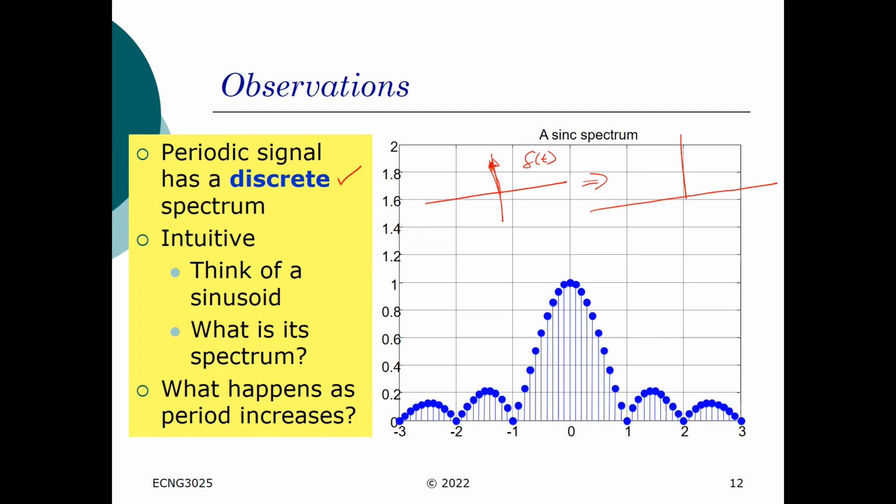If you did it, you would remember that the spectrum of the impulse, delta omega, was a continuous flat line, with amplitude 1, and this is omega. All the frequency components are there, a continuous flat line at 1 all the way through, which is why we said the unit impulse was such a powerful signal: you're imposing an infinite number of frequencies on a system.